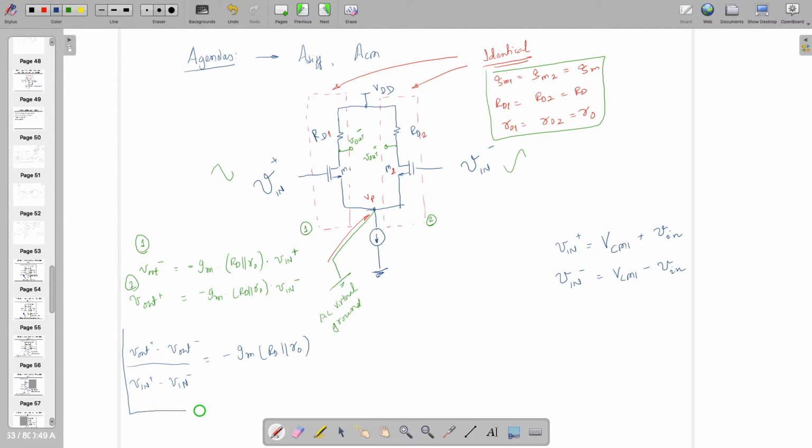So this is what is happening over here, and you're seeing this gain. It's similar to what you were achieving at the single ended. However, here the input and output are the difference of two different terminals, and that's how you're getting the double: the fundamental quantity is double, second harmonic is double, third harmonic is double, everything is double over here, because you are taking the difference of these two.